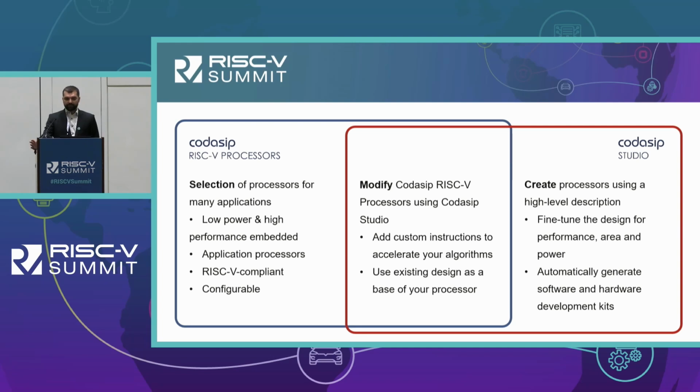As mentioned, we also have tools by which we customize or configure the cores. The main idea behind that is that the CPU is described using a high-level description language in which we capture the CPU, meaning architecture as well as microarchitecture. And then you just press a button and you obtain the compiler, low-level programming tools, simulators, RTL, verification tools, pretty much anything that you need for such a CPU.